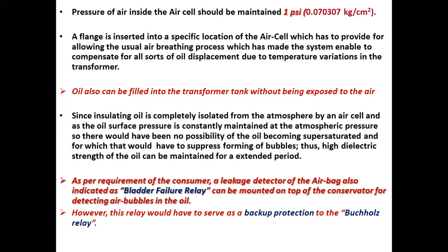As per requirement of the consumer, a leakage detector of the airbag, also indicated as bladder failure relay, can be mounted on top of the conservator for detecting air bubbles in the oil. However, this relay would serve as a backup protection to the Buchholz relay.